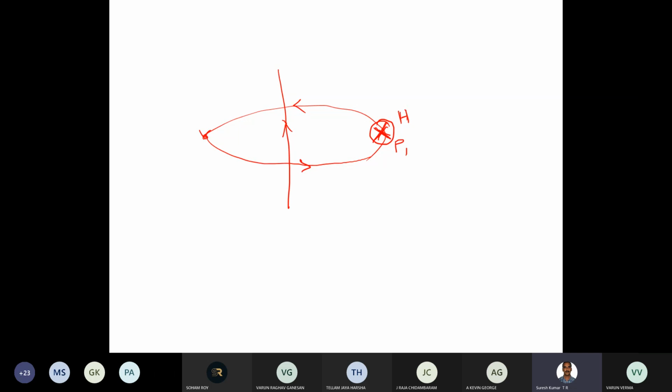And in the same way here, it is perpendicular to this screen. So you can use this symbol for the H vector. It is outward, right? Now, if you write it as a vector, you can say H along the a phi direction. With respect to this observer, it is in the positive a phi direction, right?